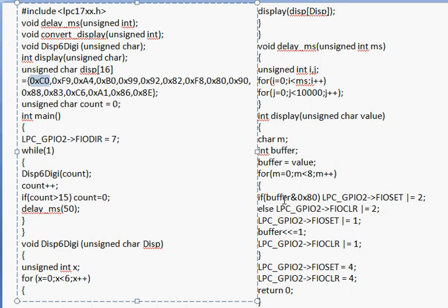If it is false, if you are not getting any result here, then bit 2 of port 2, that is P21 bit, not P20, P21 bit, make it 0, send 0. So this sends 1 if you receive 1, and it sends 0 if you receive 0 in the buffer.